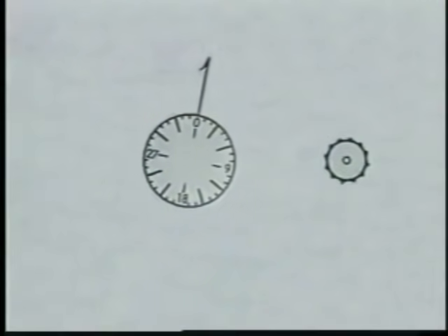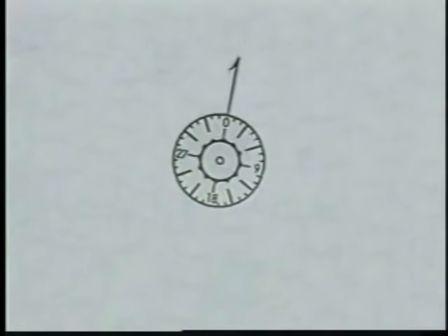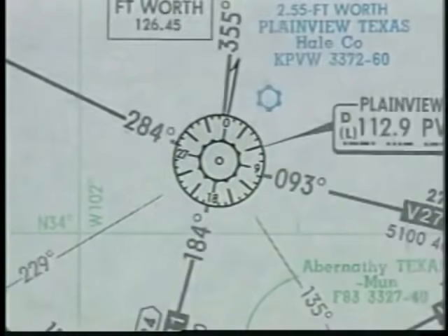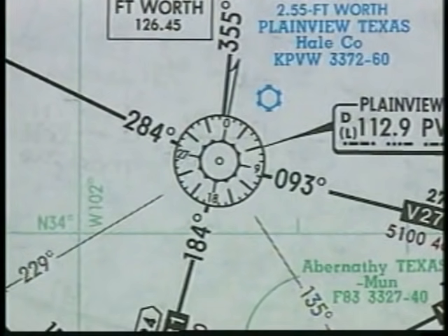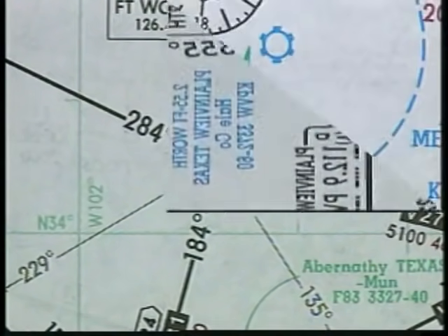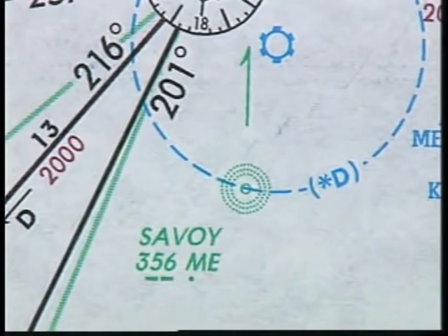When a VOR station is combined with a TACAN or DME facility, the resulting VORTAC or VOR DME is shown by combining the 2 symbols. NDBs are marked by a series of 3 concentric green dotted circles with a thin barb pointing to magnetic north. The frequency, identifier, and Morse code for the NDB are listed below the facility name.